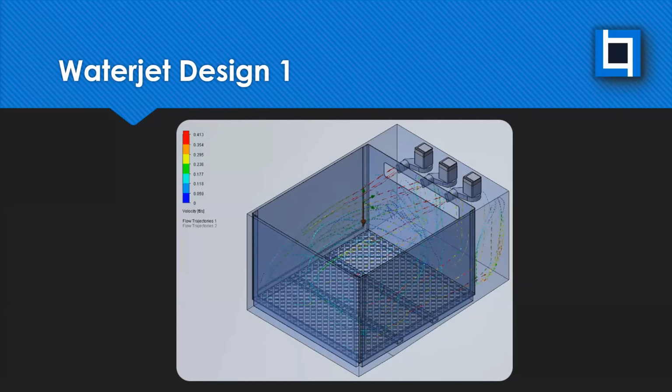And what I'm showing here is just the velocity vectors coming out of the pump. What I'm looking for is just the velocity vectors looking to some degree logical. There's no crazy offshoots or anything. The flow is quick coming out of the pump, and then as it's hitting this body of water, it's starting to slow down. You can also see where the activity is primarily focused. And then what I'll do is show you the temperature plot.